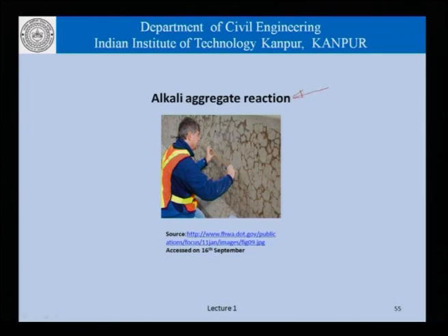So what we see in alkali aggregate reaction is shown here, that is a lot of surface cracks appear on the concrete, and they cause distress, they are visually unacceptable, and also cause problems as far as the structural behavior of concrete is concerned.